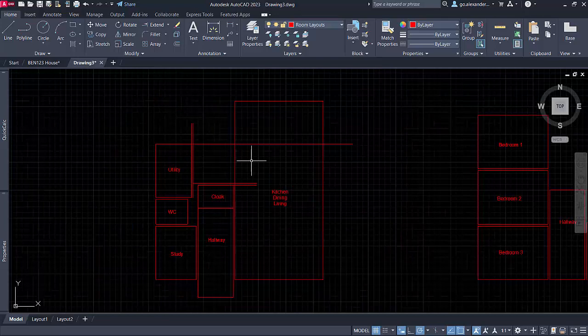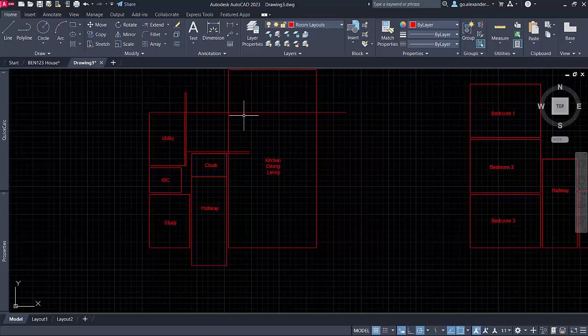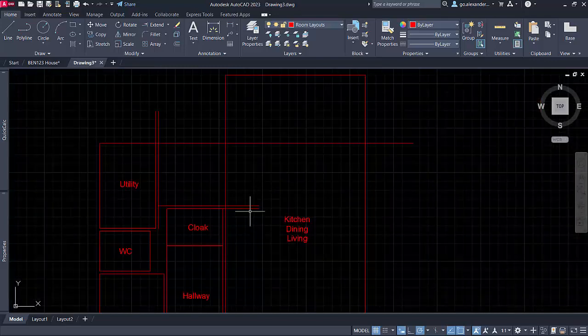And we'll make a little bit of a shape here, just like an upside down L. So we can delete some temporary lines here. And then we can use the fillet tool. Just make sure if you're using the fillet tool that you have the radius set to 0 like I have. And when you're using that, you can click on 2 lines just to trim that off.